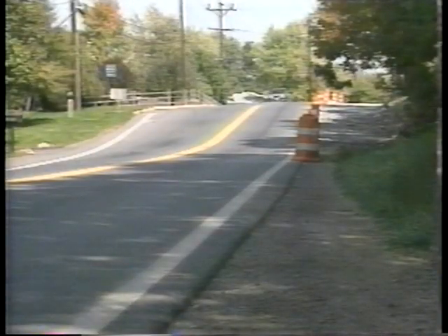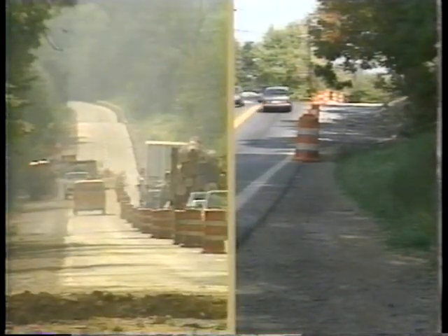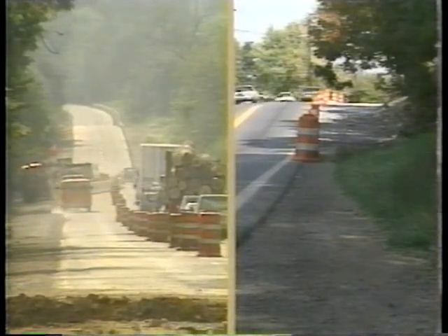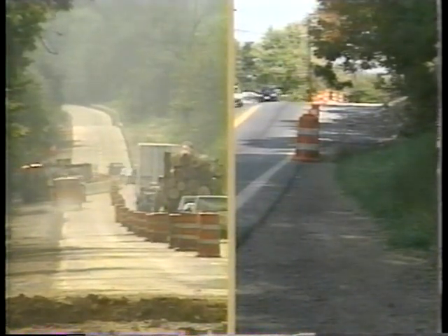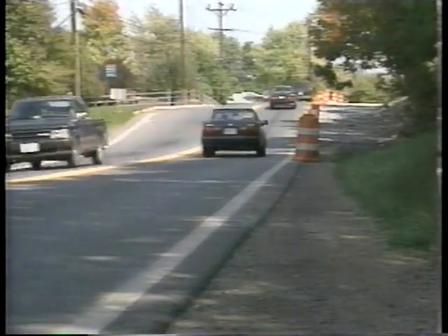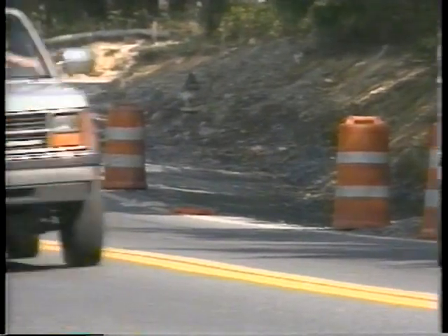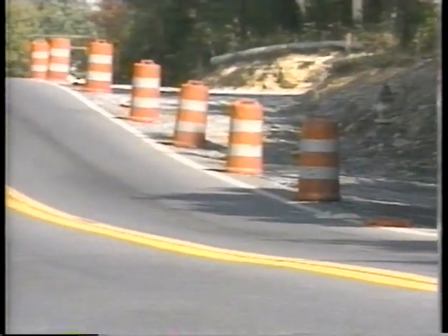There are two types of work zones: shoulder operations and lane closure operations. Shoulder operations do not actually interfere with traffic, but they do require some devices. A single warning sign and vehicle warning lights are sufficient for maintenance activity or minor reconstruction. When an improved shoulder is closed on a freeway, the work zone should be closed off by a taper of channelizing devices.